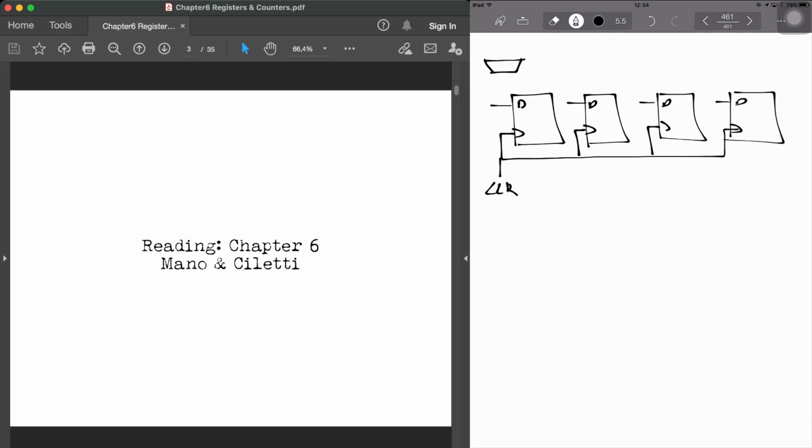A simple 2-to-1 multiplexer will work for the requirement that we need to have. So when we have, let's say, 0 and 1, when it is 0, it's going to come from the Q out.